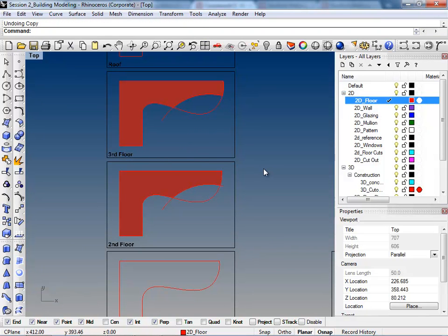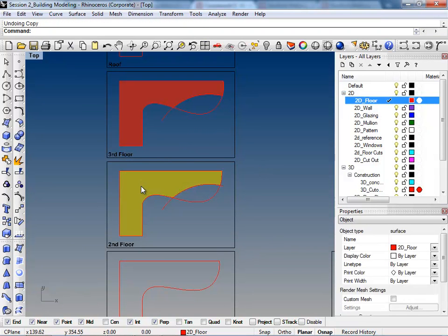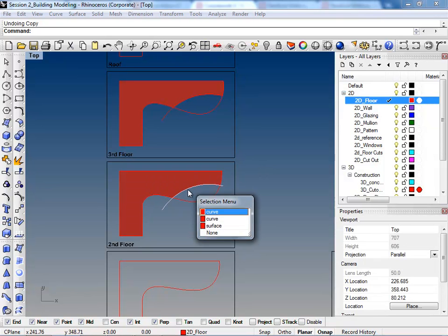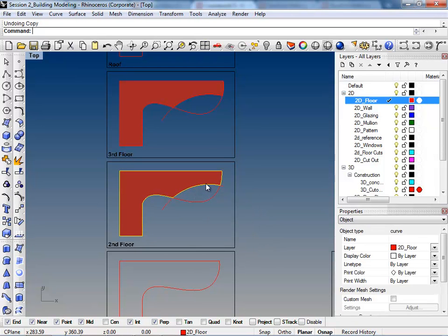How'd you make the surfaces? Pretty much once you have this exterior line selected, I typed in planar curve, or planar surface, sorry. It just looks like planar SRF. Some of the things you'll notice in Rhino, when you want to type in curve, it's just CRV, and surface is SRF, and that's pretty much two of the only things that they seem to abbreviate for some reason.